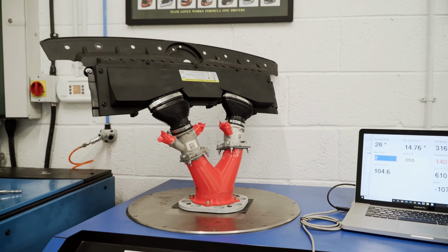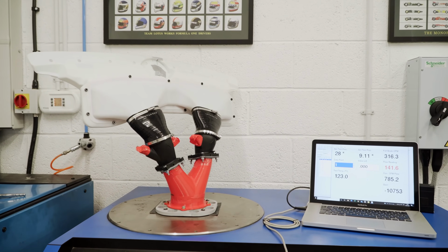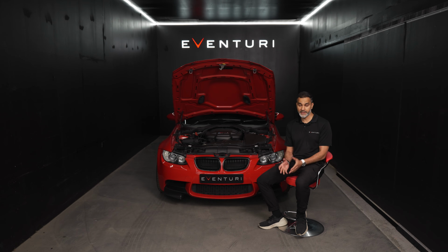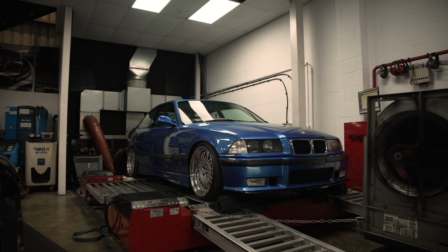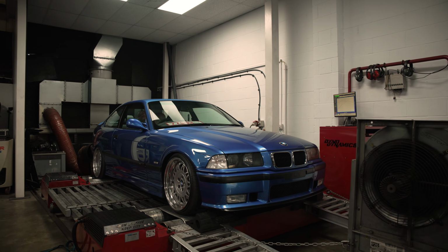One of the things we do is flow bench testing, which gives us a very accurate idea of the maximum flow rate possible through the intake. We can compare that with the OEM system to make sure that we're actually making improvements on the flow bench. The next thing we do with the prototypes is to actually take the car on the dyno for performance testing.